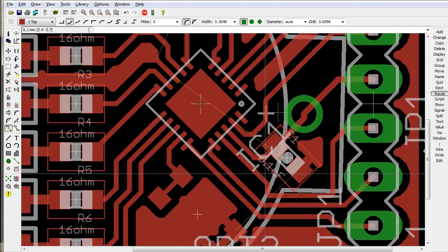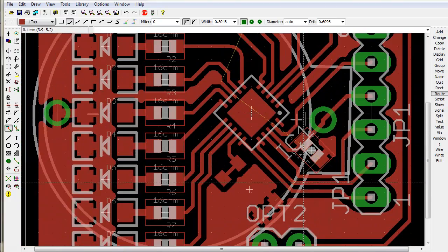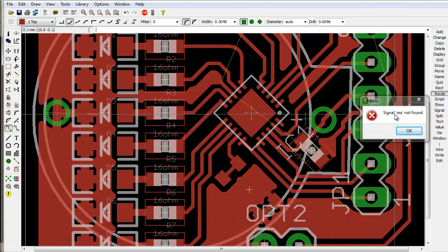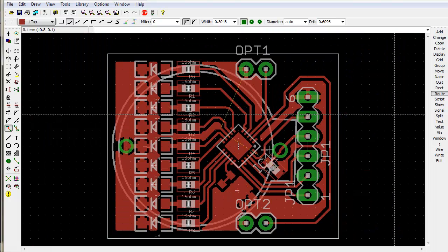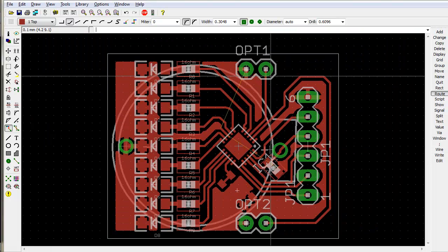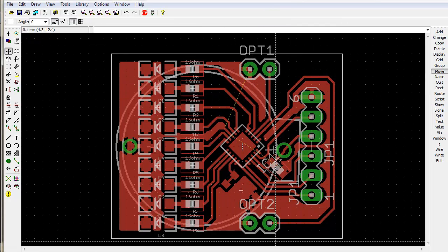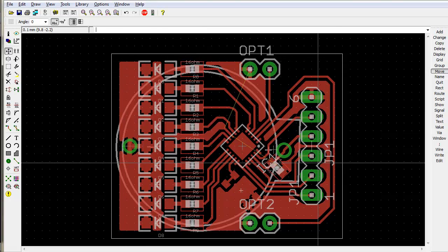There's still some wires unrouted, so let's take a look at it. Basically, we've got the same thing here. So we're going to take the wire from here and route it up here. So we're going to fill this in. Bring that in, bring that, and that's joined it to the ground plane. So we can see things are starting to heat up a little bit there. Okay, so we're going to try and get this to go over here to fill this in. So this Polygon here wants to be connected to that one, which wants to be connected to that one.